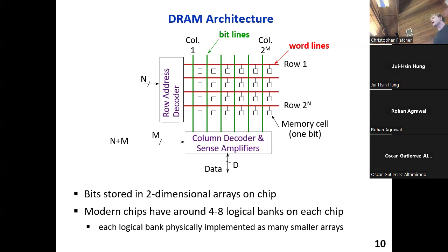If we do RAS followed by CAS, first I activate a word line and get all of the cells at that row dumped onto the bit lines. That means RAS kicks off the process of getting all of the inputs to the MUX, the column decoders, ready, so that when I finally send the MUX select signal, which is the CAS operation, the inputs are ready, and I can get my outputs out.